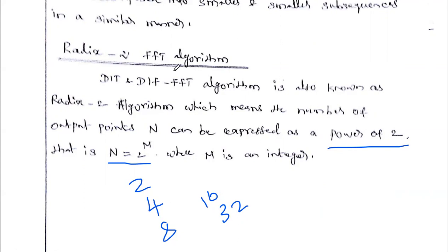So using this FFT, we can perform 2-point DFT, 4-point, 8-point, 16-point, 32, 64, 128, etc. That is, only powers of 2 can be obtained. So there is no 6-point FFT algorithm, and no 15-point FFT algorithm. The number of outputs produced is always a power of 2. That's why this FFT algorithm is otherwise called radix 2. So this is also one of the important 2-mark questions.